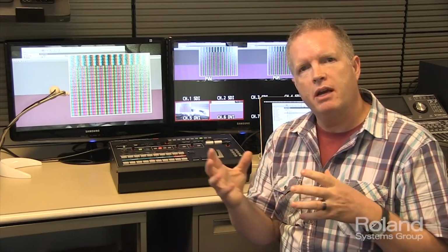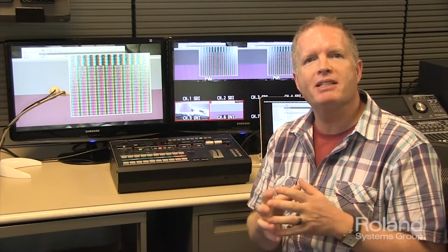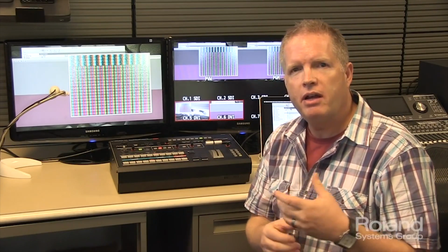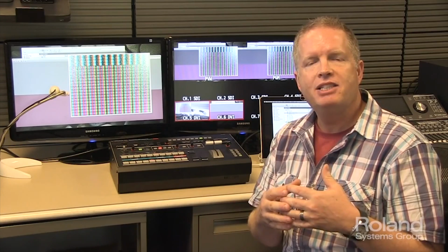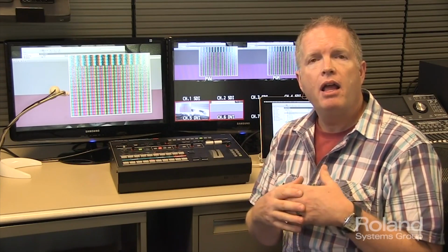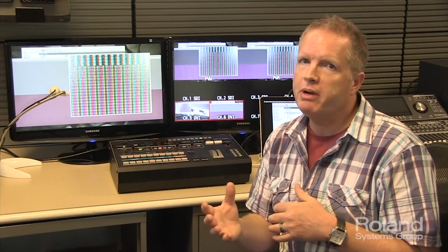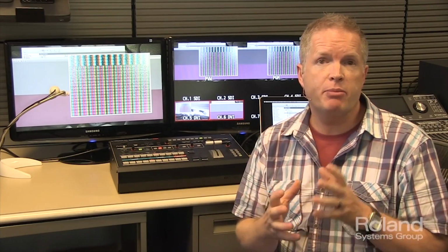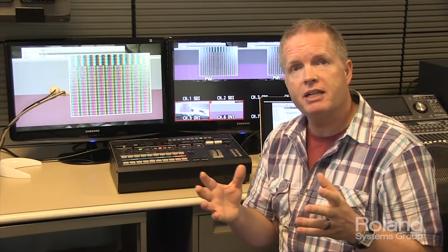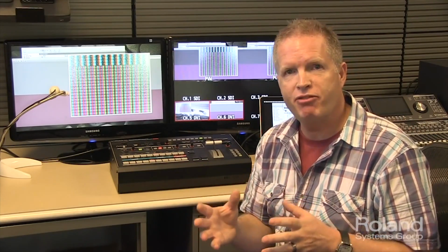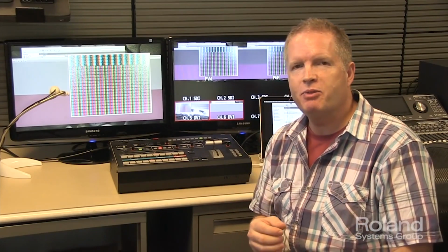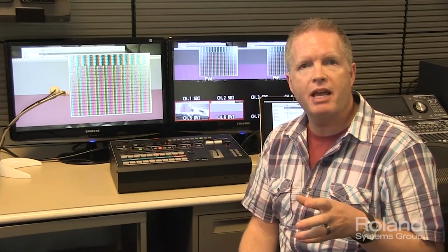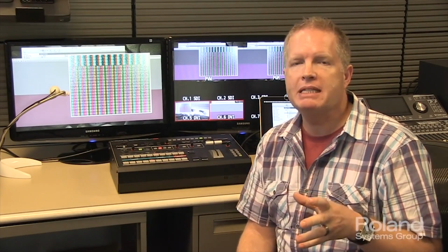So what scientists were able to do is compress color in different ways that the eye couldn't really detect very well. Our eye actually detects changes in brightness, luma, much more readily than color. So usually we don't compress that part, which is the first number of the four, but the other colors we can compress and get away with it, especially in the video world. Where you can't get away with it as readily is when you're using computer inputs. So today I want to show you some practical examples of how it really makes a difference in real life.